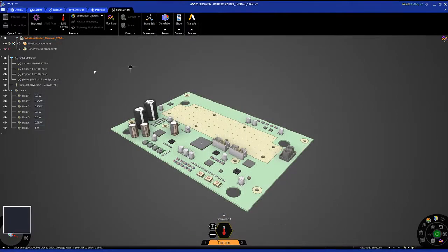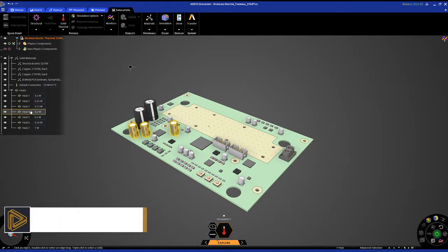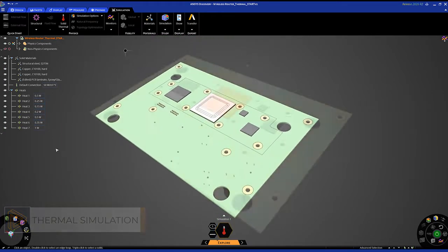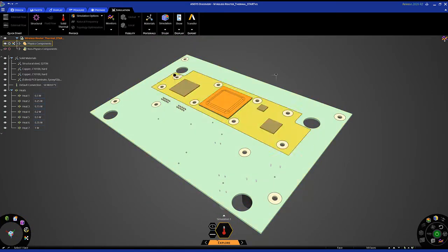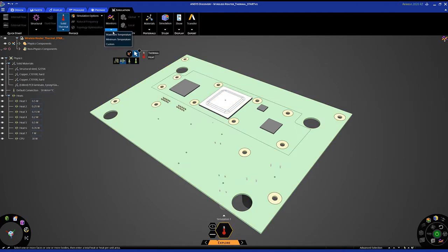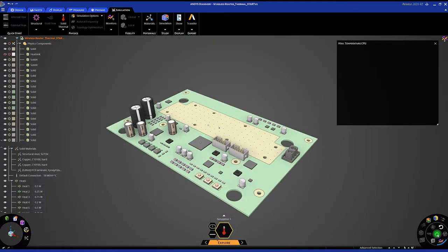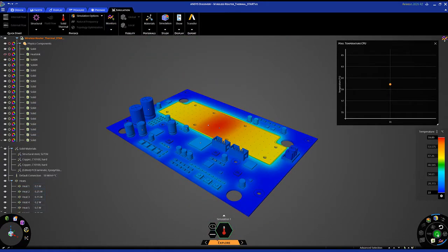Let's look at a thermal study where I'm working with an electronics enclosure. We have a control board and multiple heat sources. My goal here is to perform a basic simulation of temperature on the control board. After applying a heat flow of 30 watts to the large body and setting up a max temperature monitor, Discovery quickly displays a temperature and capturing it on a plot. You'll see I'm sitting around 60 degrees Celsius on the top face.